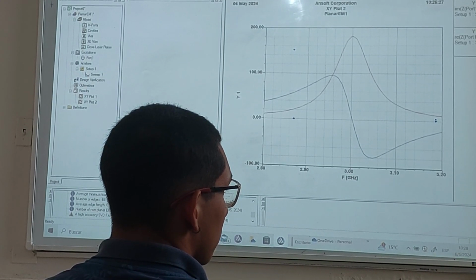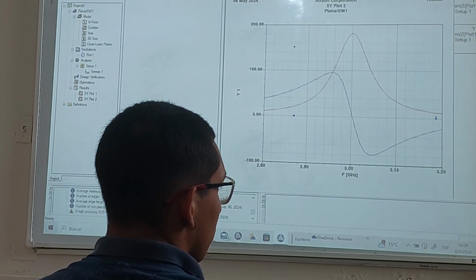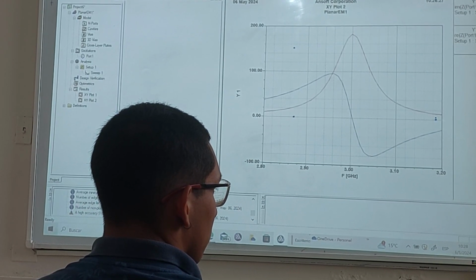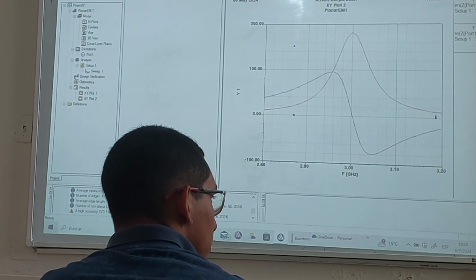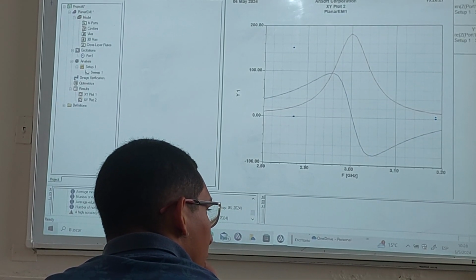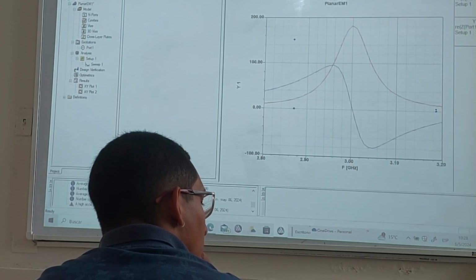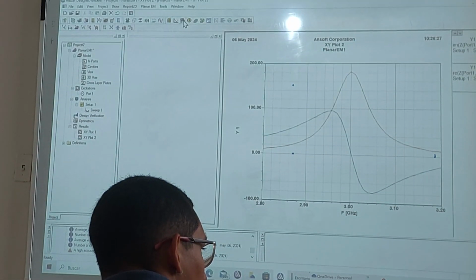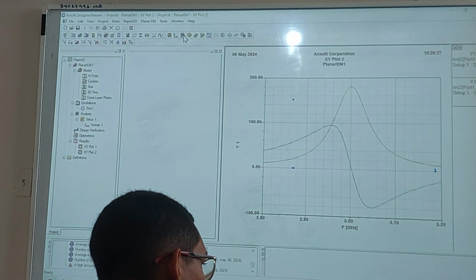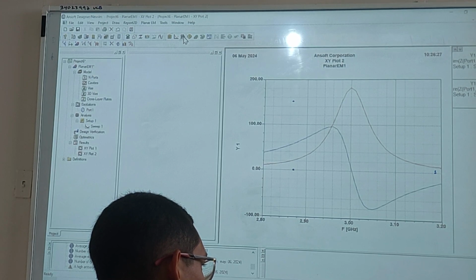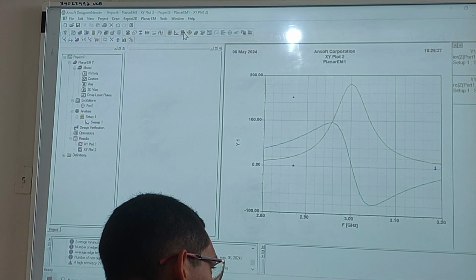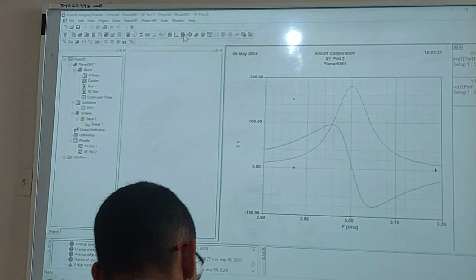If we have a low impedance, it means that the impedance we put here has a wide width. Okay? If we choose a high impedance, it means that this impedance, say A, has a high value. If we have a high value, the width of the transmission line is small.